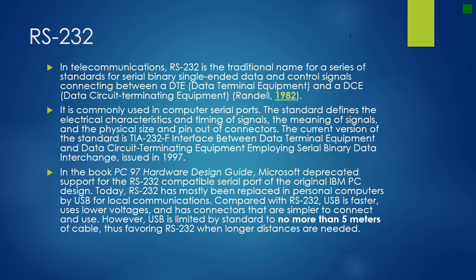For RS-232, only the voltage of signals and the functions of the physical interface pins are standardized. So for RS-232, you can directly program or interface using your computer, unlike USB, for which you need another circuit or software to interface the I/O ports.